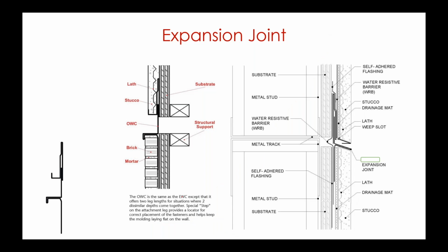All right, let's talk about expansion joints for a minute too. You have different types. A lot of them will have this flange right here. Now what happens with that flange is, if I've got an acrylic finish coming over this and it seals up to that flange, my water that's coming down is trapped. I just closed off my exit door. Where's that water going to go? Typically, it's going to feed around that water-resistant barrier and start working its way back up.